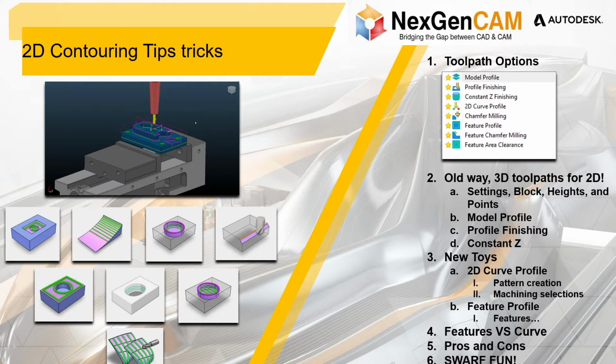And as you can see here in the list, I have the old way versus the new way, basically. And for all of those PowerMill users who've been with us for a very long time, and individuals like myself have been using it since the early 2000s, we got used to creating 2D toolpaths using 3D toolpaths. That's because we didn't really have the tool sets for 2D chaining and things like that in the original versions of PowerMill. However, we have added those new toys to us.